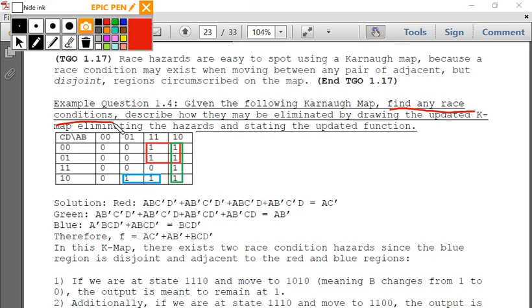So we had this AC not, AB not, or BCD not, right? And then we come up with our race conditions, and what happened to that equation? It got expanded, right? So when you have an expanded equation, how does that apply to the actual circuit? More complicated, right? So we've now created a more complicated circuit, which consumes more power, and so has slightly higher area, right? So those are drawbacks, but what's our positive?